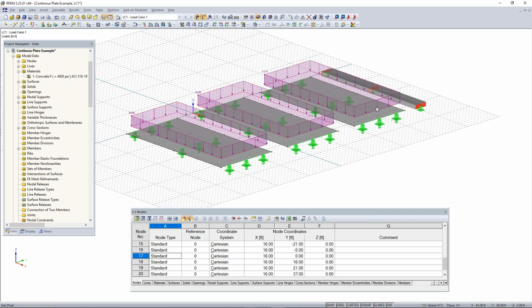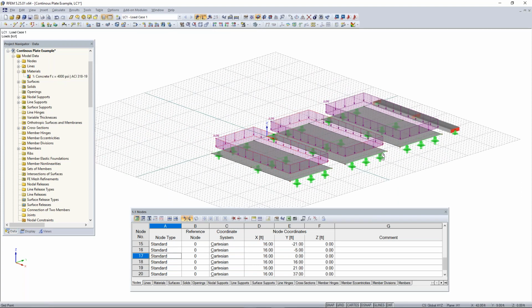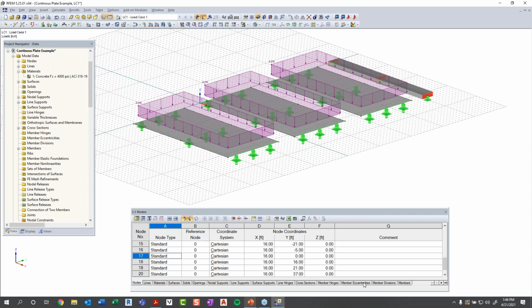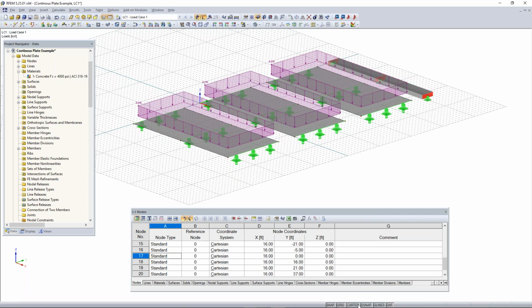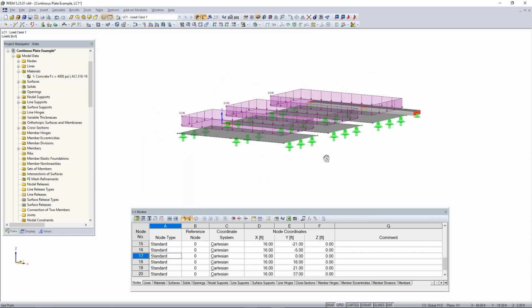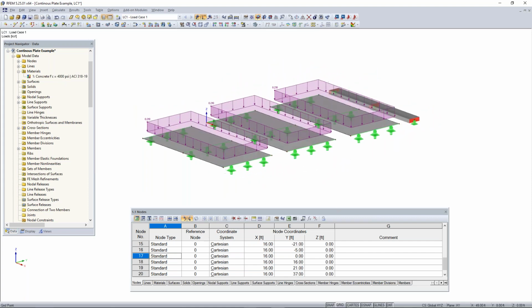I can also turn off this grid in the background now that we're done with modeling to get a cleaner look. So I can go down here and you can see these options down here are buttons used to turn off certain functions like snap, grid. You can also change your grid to a polar grid. We'll keep it as Cartesian. And then you can turn off some other things like guidelines as well. So we'll just turn off the grid, and now you can see we have just a cleaner look, better for presenting.